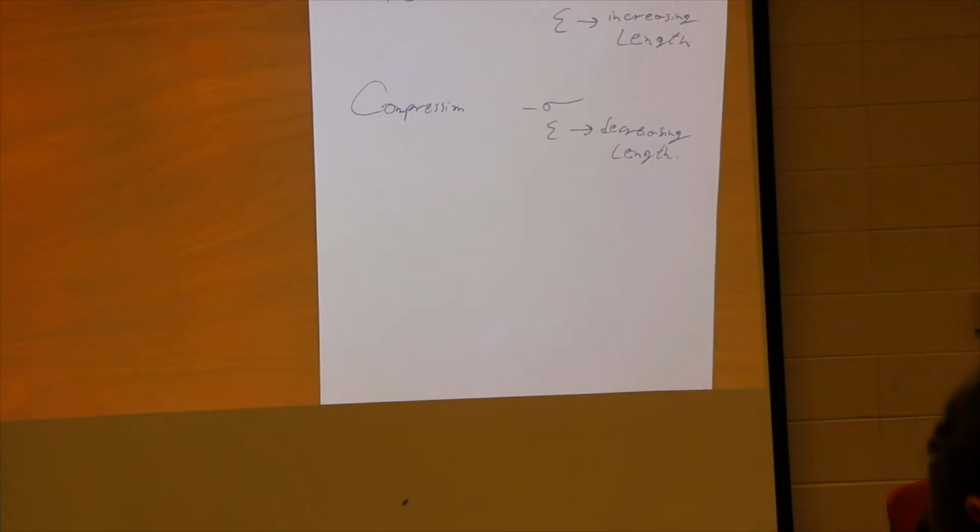All right. So I thought X was in tension. Well, X is tension. No, but when X is in tension, it is decreasing in the opposite directions. Because if it's elongating in X, it's decreasing in Y and Z. And if it's compressed in Y, it's bulging in the other directions. So that's why this formula is a little bit confusing, and that's why I have to be careful.